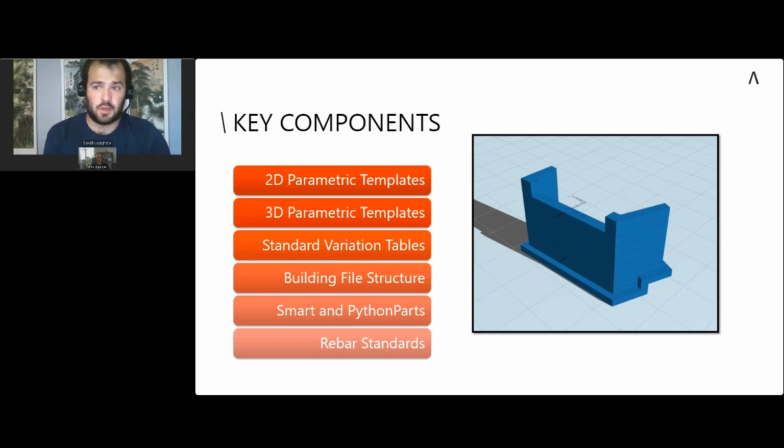What we do is basically we load this model and we start adding in additional detail. We load this model within a given DOT's workspace with a given DOT's CAD standards, and we start modifying it and adding detail. And by doing so, we've saved ourselves a great amount of time in setting up the structure of the project. We've saved ourselves a great amount of time in loading in template files, in stitching together the variations and the parametric and metadata that actually turn this thing from just massive 3D solids into a model that knows what it is and knows how you can control it, and allow you to get straight into the business of actually changing this model from a very generic one into a bridge that is your bridge.